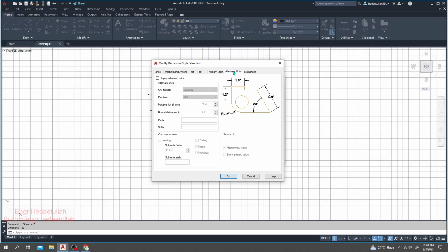Okay, now after that, you can change it for alternate unit. So what is the meaning of alternate units? Just see, they have a unit, it's showing 1.2 inch or here 2.0 inch. So if you need to show your value with another different unit like mm or like inch or like feet, so how we can do that? I'll go for display alternate, and here what will be your value? If you provide engineering with that value, then it's giving you value here.